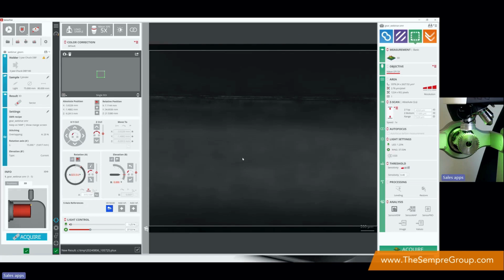The first measurement I'm going to demonstrate today is a form measurement. To do that, we need to choose focus variation. You can see that here it's already selected, as we are on the green icon, but if you need to change technology, it's as easy as switching between icons. The lens I'm using is a 5x epi lens. This is because it has a wide field of view and it's perfect for this sample.